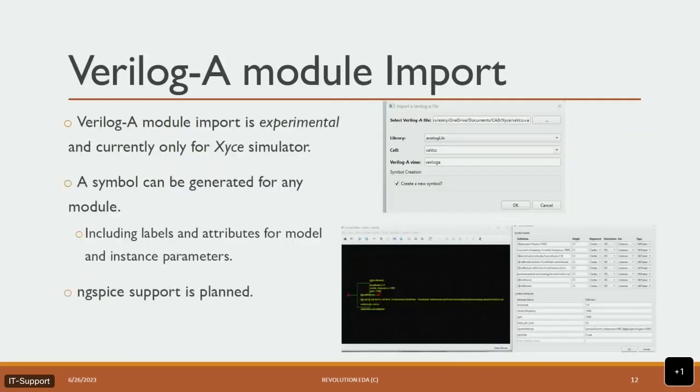So you can, at the moment, import Verilog-A models, and it will create a symbol. And when you create the netlist, all the information will be there. This is a preparation for creating a simulation GUI. At the moment, it is really geared towards Xyce, because in an earlier incarnation with Glade, I did some Xyce GUI. But that could be done with ngspice. I dabbled with OpenVAF a bit, but didn't have too much time to really test drive it.